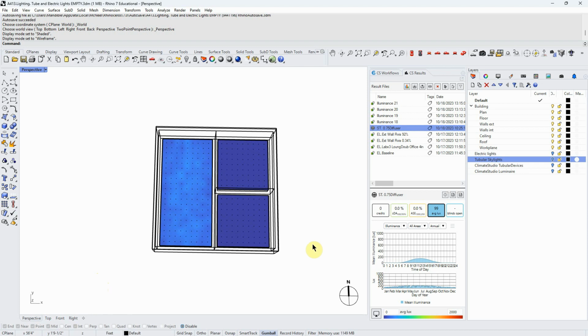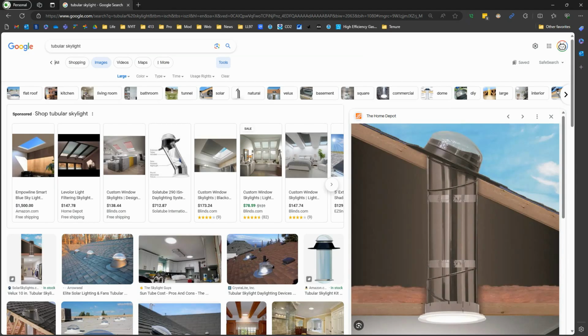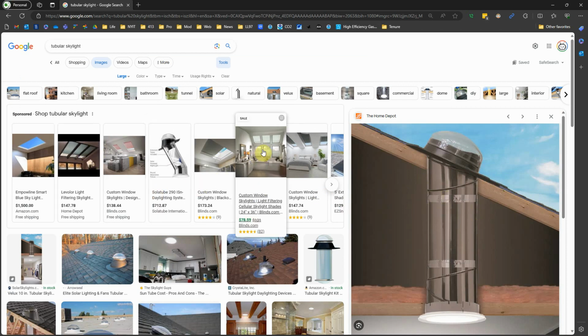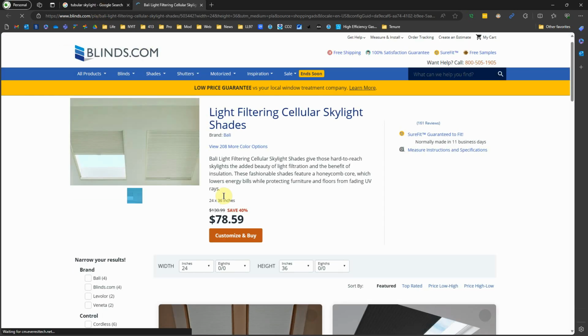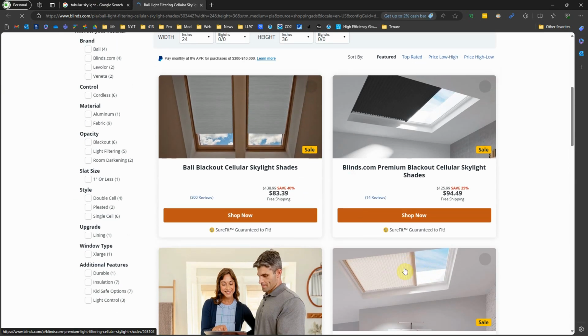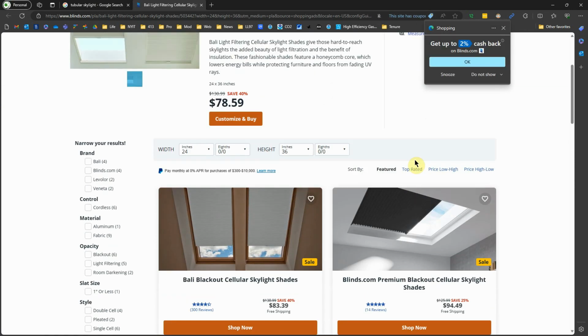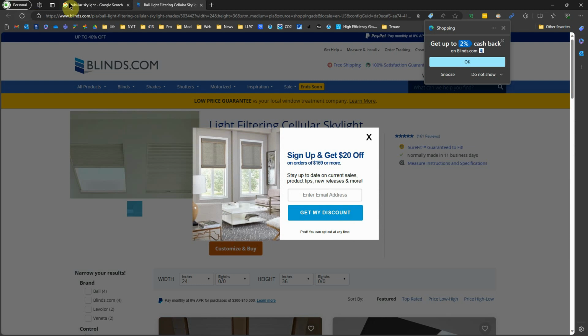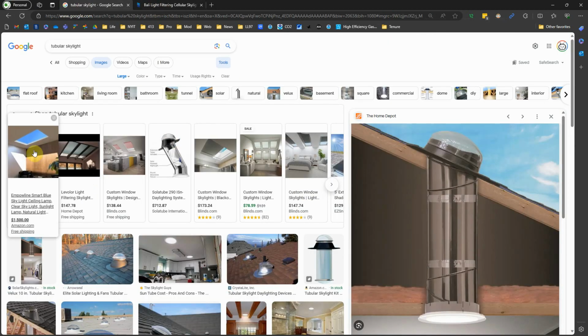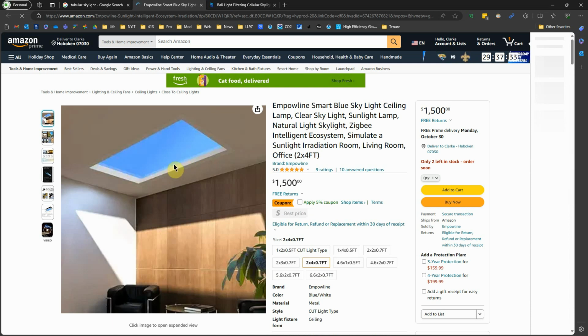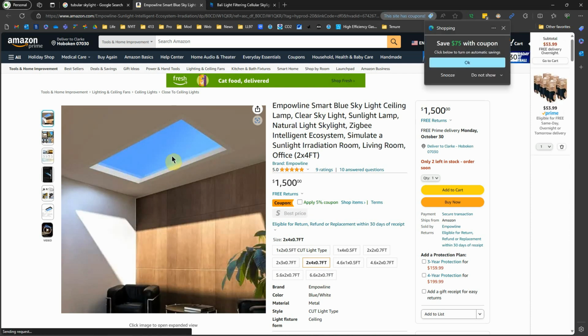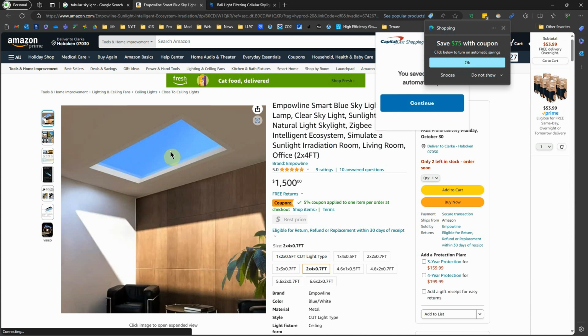Let's talk about adding the option of tubular skylights. What are they? If you think about this skylight here, that's why there's blinds on them. In the summer, there's a huge amount of light coming in through overhead skylights, so they can be very inefficient or ineffectual, like this one. It's going to really overheat in the summer. You're going to get heat loss through it in the winter, and you'll get some gain, but you won't really be able to spread it or control it.